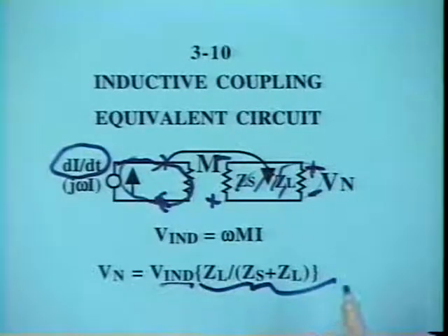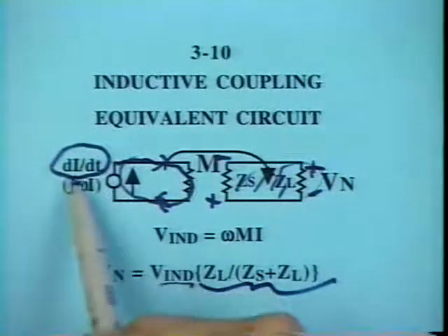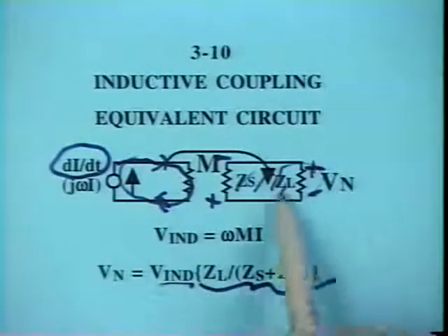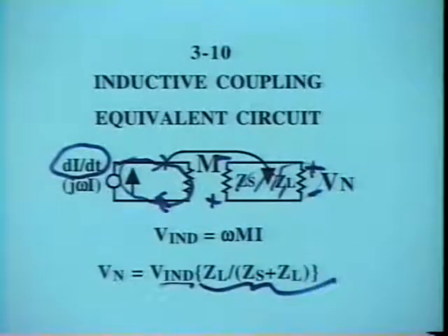So what indicates a problem magnetically is a significant amount of fast switching, pulsing currents, a little bit of extra loop area, and a high impedance circuit, a high impedance load end on the circuit.